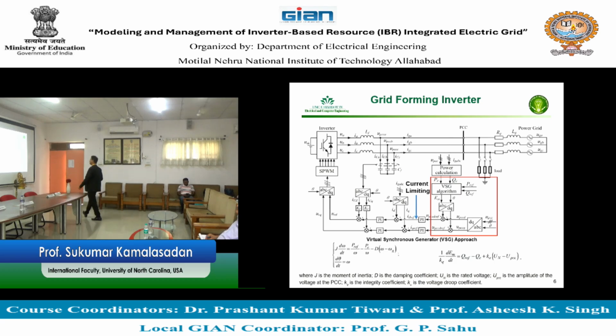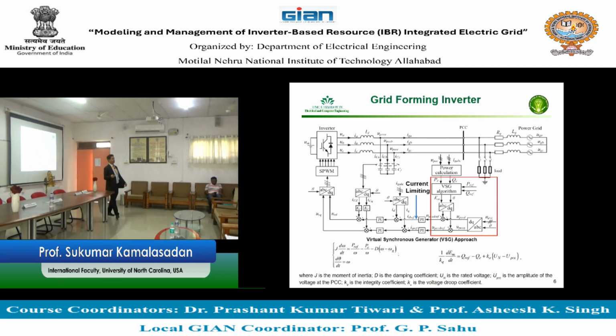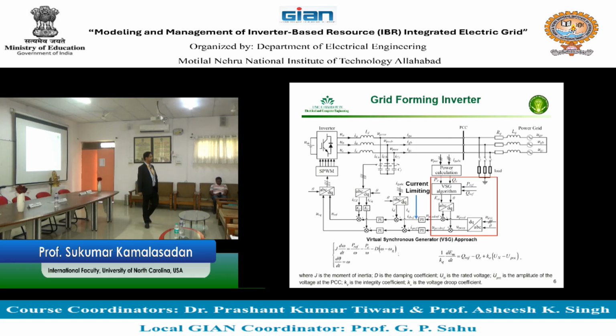Now you may ask the question: can I model an excitation system? We said swing equation, the two model. If you go to the second order differential equation for the synchronous generator, we call it the swing equation. If you go to higher order, I don't know whether you have seen this generator model. You can look at it in Simulink. The generator model is there up to 8th order.